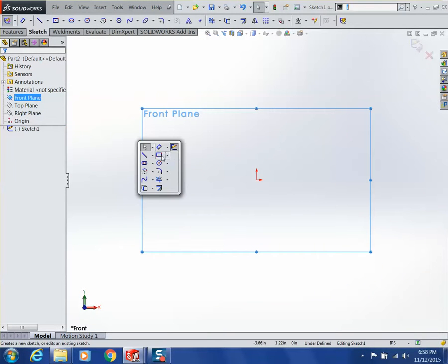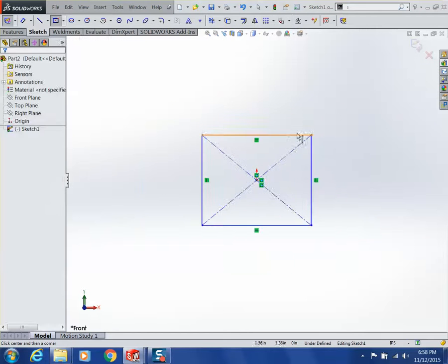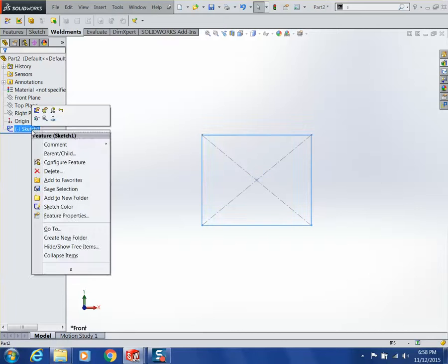If you're going to grab anything that's in there, go grab an existing one and copy it whenever you can. That's good practice just in general. Why remake it if you can copy something to start from? SolidWorks has a set of those you can download. Parametric, where you pick a configuration, and it maintains the face IDs as well. And there's hundreds of them. If you want to start getting into this, like I said, there's a lot of people who spend a lot of time making this work really, really well. In my case, I made the lumber profiles just because there were a couple of sizes I had to play with. It's good experience to go mess with that.